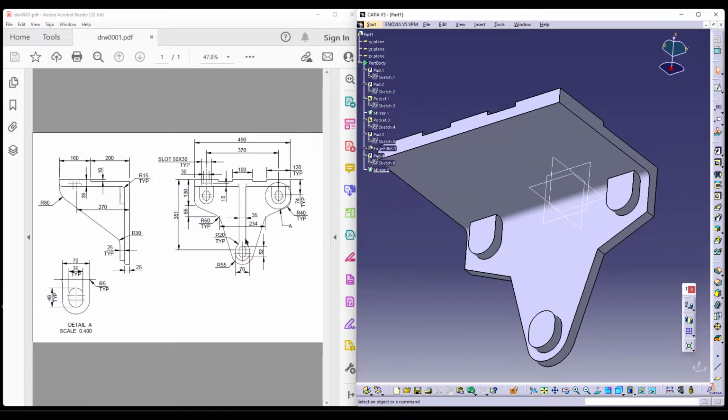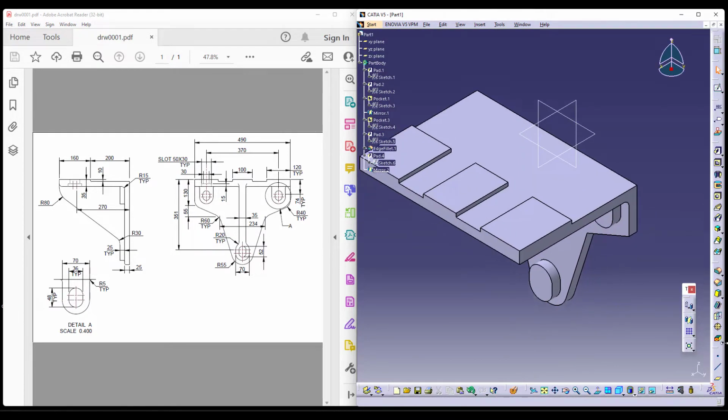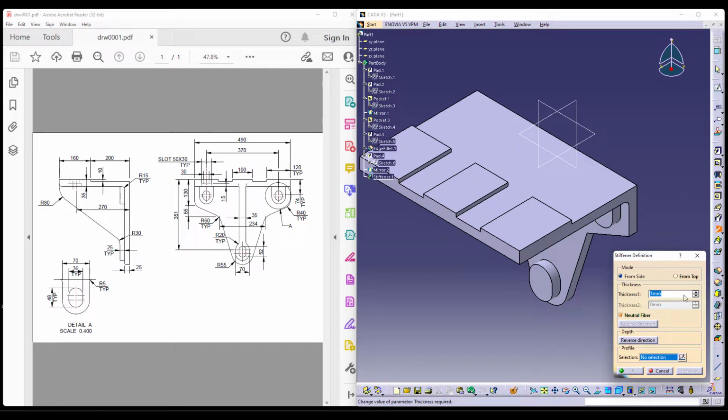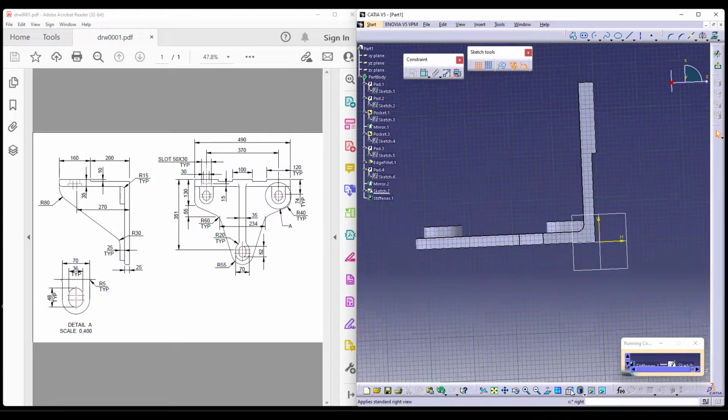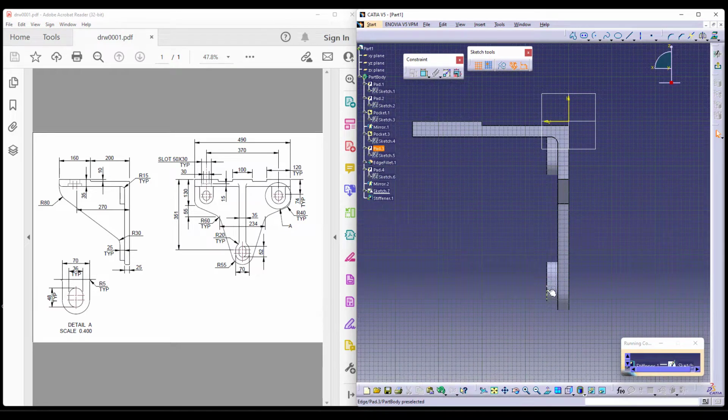There is a rib which you can see of 35. So let's try to add that. This rib is stiffener in CATIA. There are different type of stiffeners. So under this you can see the stiffener. Let me try to make the sketch first using the right plane. Again, I want to go back to my right view and give the references whatever I need. These are my references. I do not need anything else apart from this. If I need, I will take them a little later.